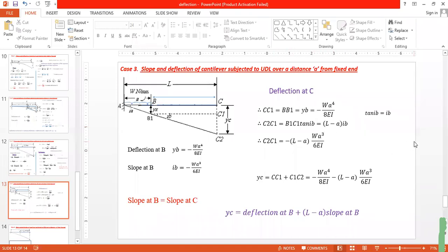See here, in mechanics of materials, or structural mechanics, high deformation is not allowed. If you get high deformation or high deflection, then it becomes plastic deformation. That is not acceptable, and these theories are not applicable for plastic deformations. Plastic deformation theories are very different from that. In the whole content, our assumption is that deformation is very small.